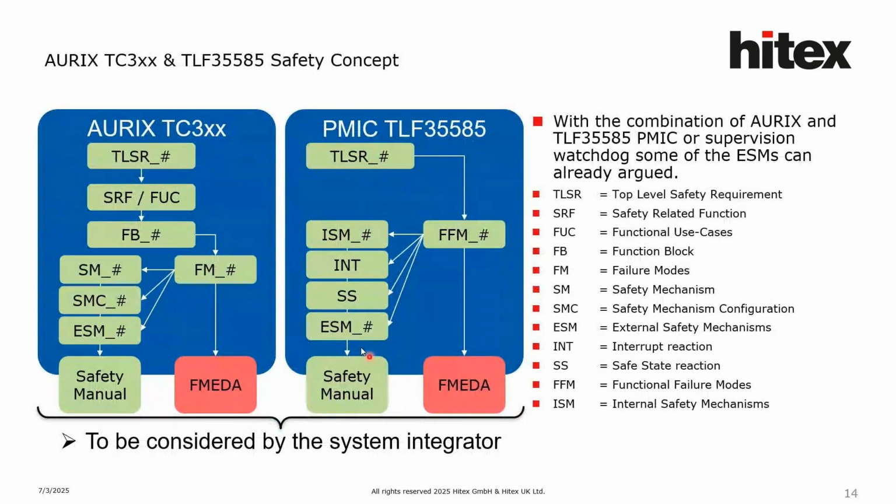So for a customer project, the AURIX needs a power supply, and we recommend to use the Infineon PMIC TLF35585 B30 step as the best power supply and safety supervision solution. For a safety project, the system architect and the integrator have now to combine both ICs. All the documentation, all the Excel sheets are to be considered by the system integrator in a smart way to save time, increase the availability, as well as the performance, and of course to ensure that the safety goals are